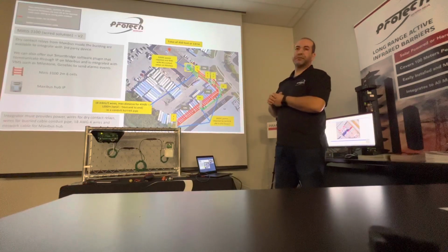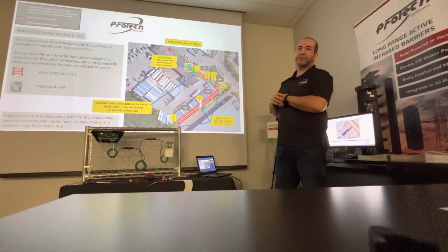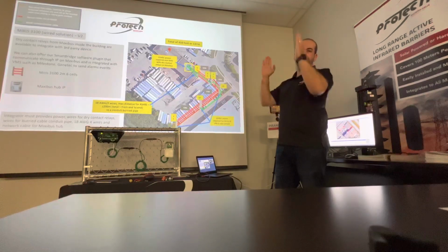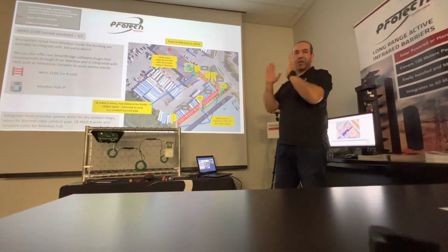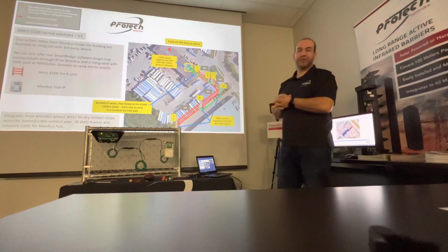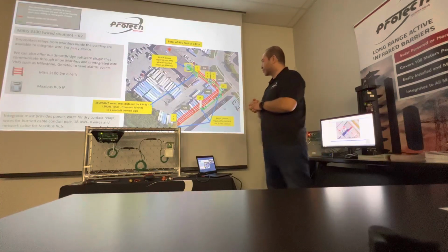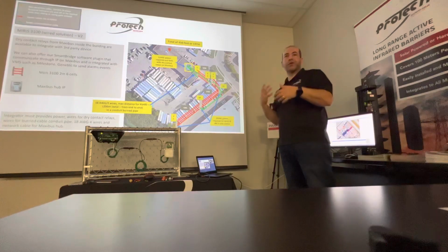So you have to set the dip switch on each specific section of fence between the two. I mean, not fence, your infrared barrier. Yeah, the infrared, that's what I mean. Exactly. Like this column and this column right here have to be set to say channel 1. Yeah, so transmitter, receiver, channel 1. That way you know it's each pair within this zone. Of course. And this is the process usually during the commissioning.